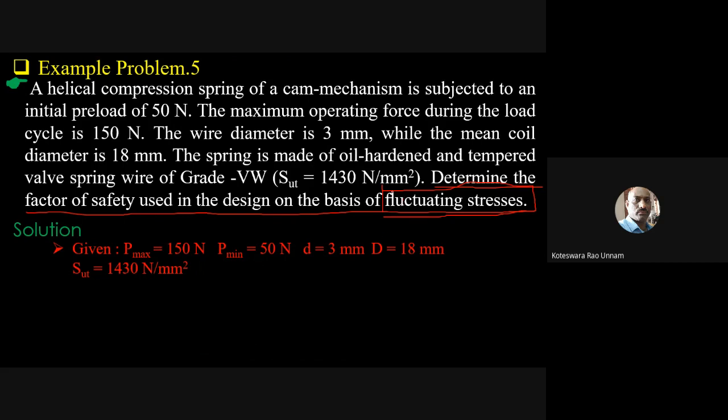If he has not mentioned anything about fluctuating stress in the problem, if this word is not there, don't go for the design against fluctuating load. Even though the load is varying, let us say in problem 2 the load is varying from 300 to 150, even though the load is changing, we still use the static design procedure for static loading, not the fluctuating load. If the words fluctuating stresses are in the problem, then you have to use the fluctuating load equations. Anyway, we'll discuss this problem in the next class.